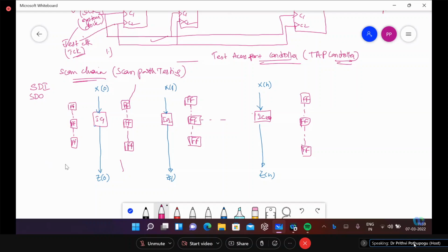These flip-flops communicate the data to the IC under test and store the response from the IC under test. Now this becomes one segment. The same register output can be connected to communicate the previous response.